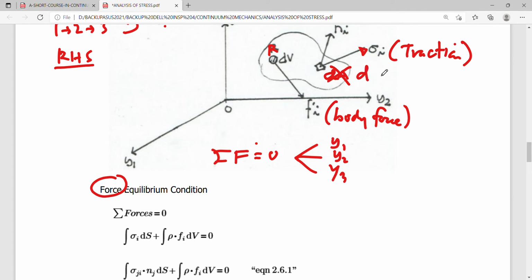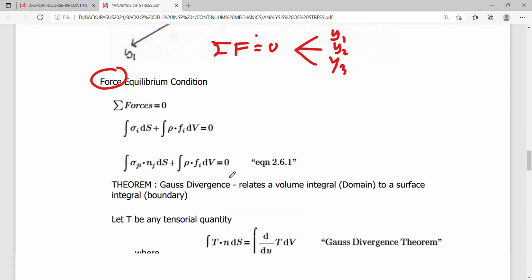Your total surface area is considered S, and the traction force, which is located at the point P, will be defined by the differential S, upon which the orientation of the surface is defined also by the normal vector Ni reckoned from that point. That's how this system of a continuous body is described based on continuum mechanics.